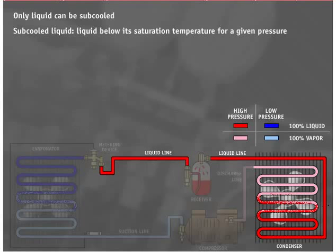Another method of subcooling liquid, called liquid pressure amplification, is covered in the section on superheating and subcooling. This method increases the pressure on subcooled liquid, causing it to be subcooled even more. This creates a liquid with a temperature below its new saturation temperature for the new higher pressure.